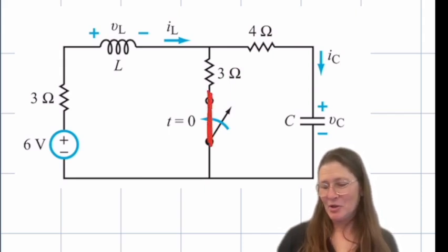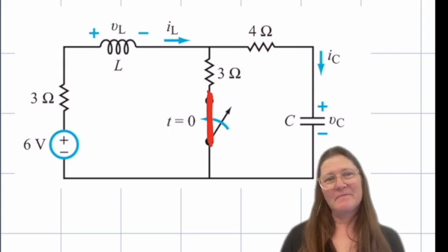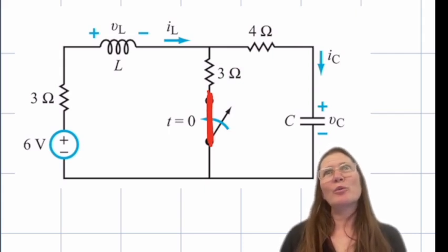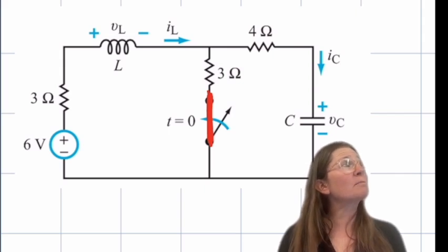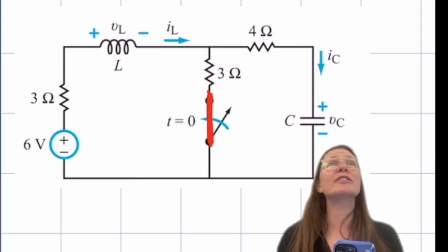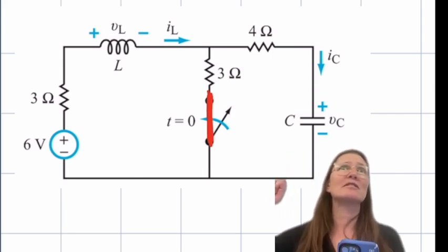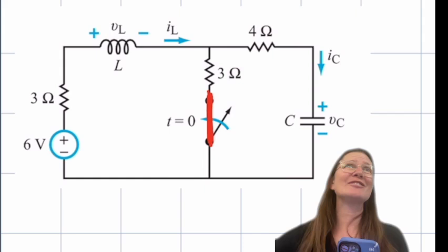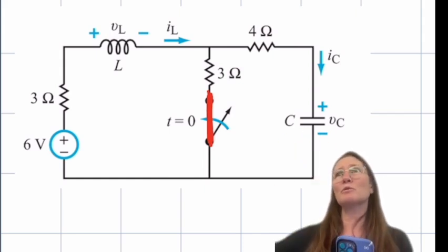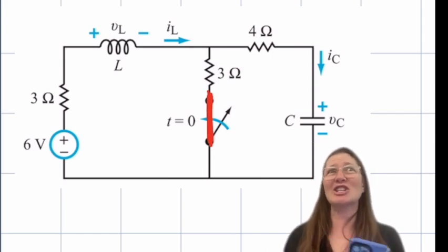So this would be closed. What makes this one tricky is that in order to be in parallel, they need to have the same voltage across both their branches. In series, the same current would need to flow through them. Correct, neither in this case.